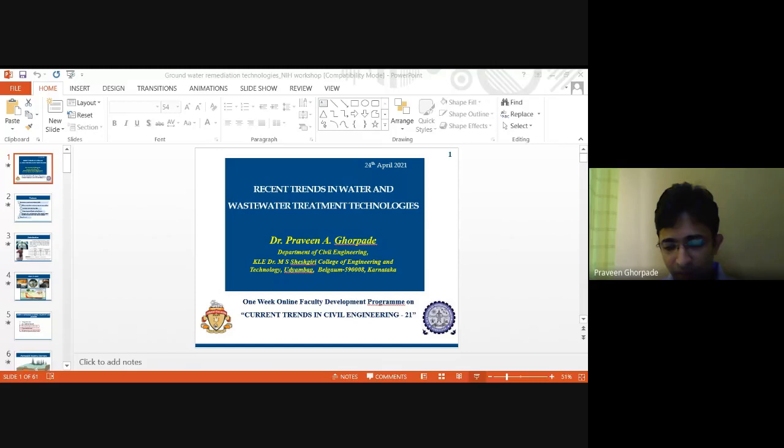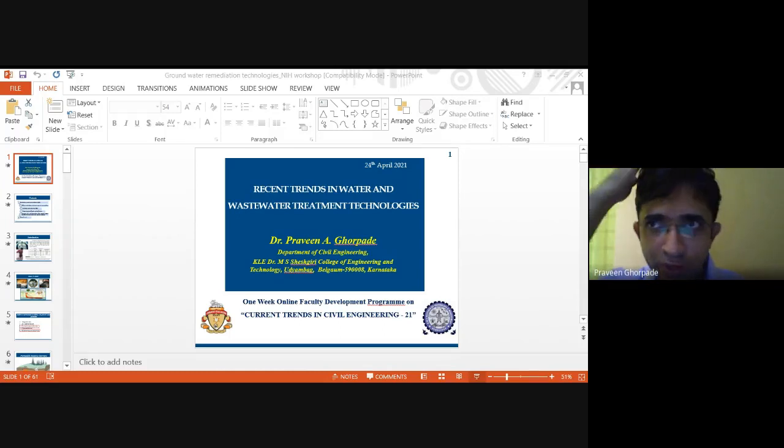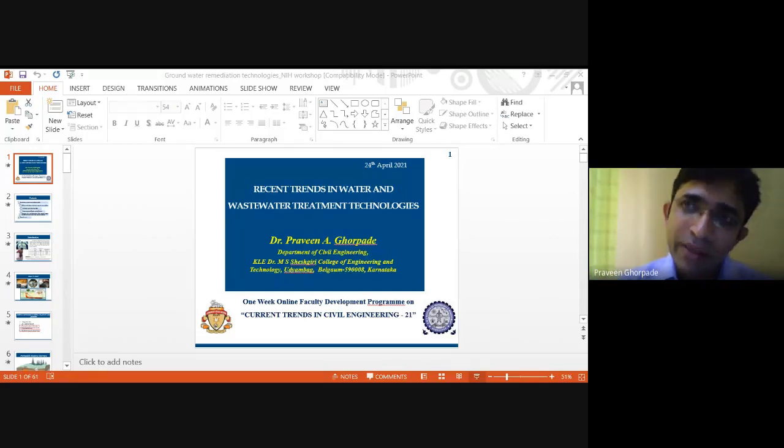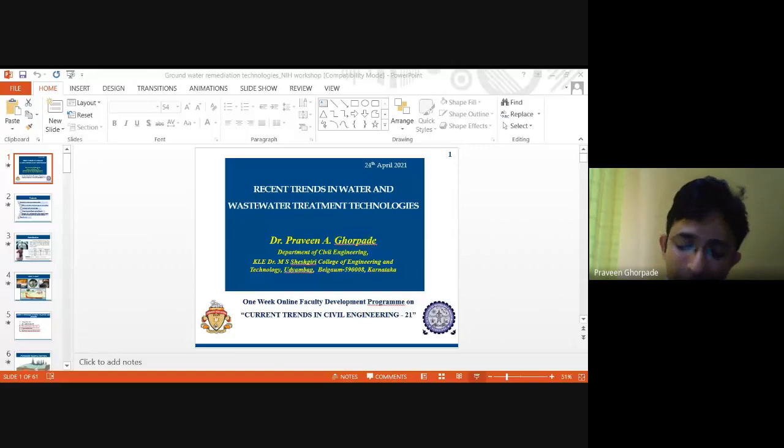For example, in India, we use chlorine as a disinfectant for disinfecting the water. But the research which I saw in 2009 in South Korea was studying the adverse effect of chlorination on human health. Of course chlorine is used for disinfection, but they are studying its adverse effects. There is something called NDMA, a kind of complex organic, a nitrosamine, which gets generated because of chlorine combining with the organics of the water, and that is known to be a carcinogen. So if you put excess chlorine in the water, how exactly is it going to adversely affect human health? They are studying those types of problems.